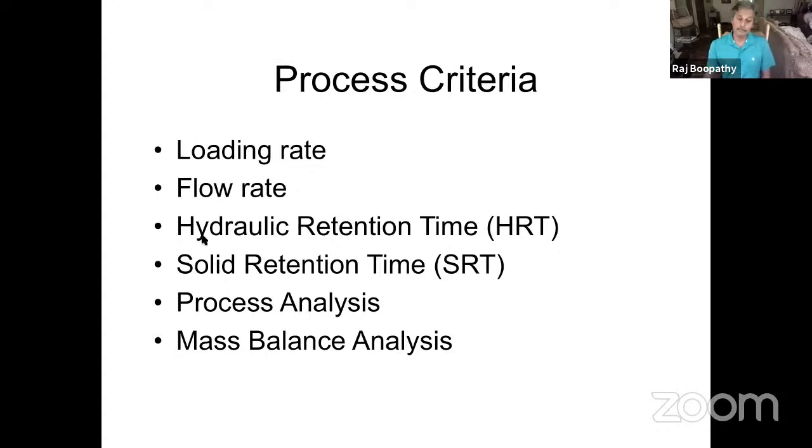But at the same time, you need to treat your wastewater as fast as possible, because time is money. You want to treat it as fast as possible to meet the regulatory standard. So you want to keep your HRT short and your SRT long. When you design a system, that's what most engineers calculate and do.